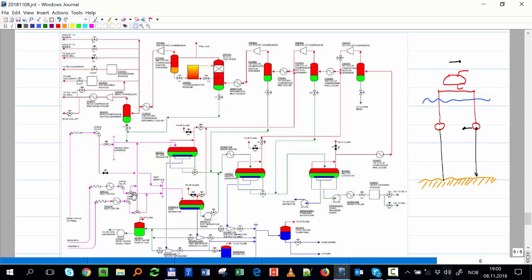So let's continue. Here you see you have the choke valve, the choke of that well. Now let's follow. What do we follow now? Let's follow the water first, which is slightly simple. The water goes to the water treatment. In that case, I don't have much space, it's very compact, so I use this symbol of a hydrocyclone. It enters tangentially and it has a very high rotational speed.